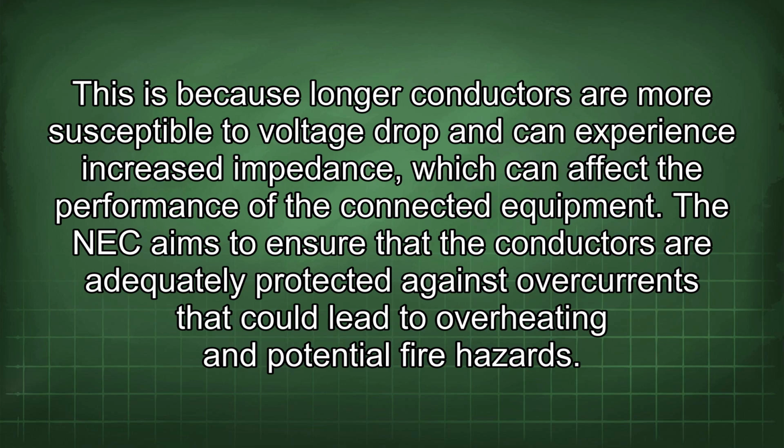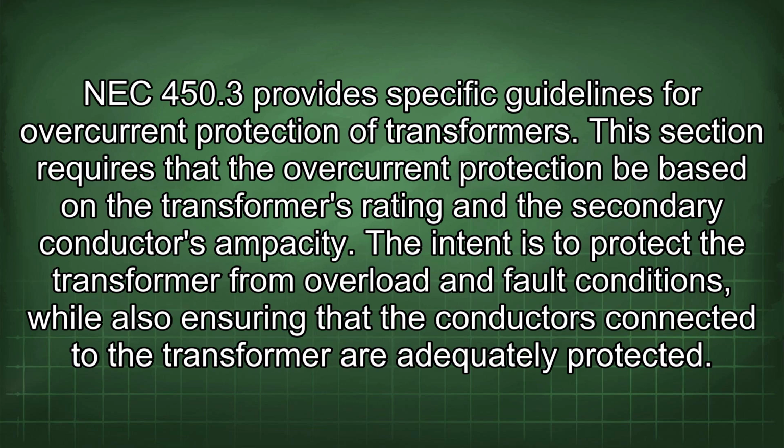The NEC aims to ensure that the conductors are adequately protected against overcurrents that could lead to overheating and potential fire hazards. NEC 450.3 provides specific guidelines for overcurrent protection of transformers. This section requires that the overcurrent protection be based on the transformer's rating and the secondary conductor's ampacity. The intent is to protect the transformer from overload and fault conditions, while also ensuring that the conductors connected to the transformer are adequately protected.